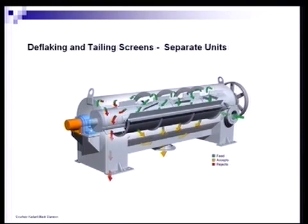Following a secondary coarse screen is often a separate tailing screen. In older mills, these might be vibrating screens, but in more updated versions is an atmospheric screen, such as this, where it uses a half of a screen plate laid down into a frame, into which a rotor is placed, and there is about a 1 millimeter gap between the rotor tip and the screen plate, so that as you turn the rotor, it keeps the screen plate clean.